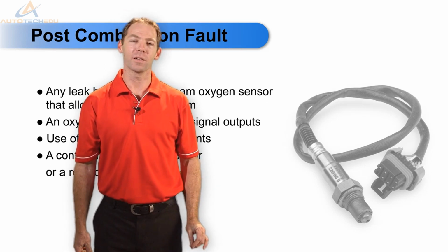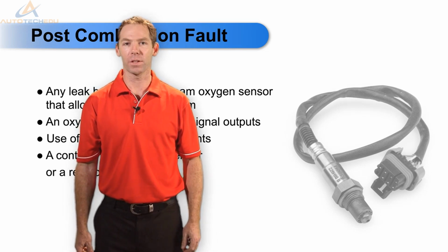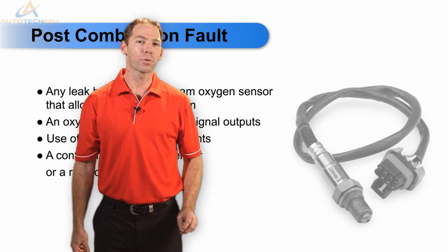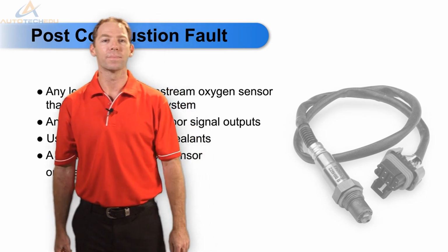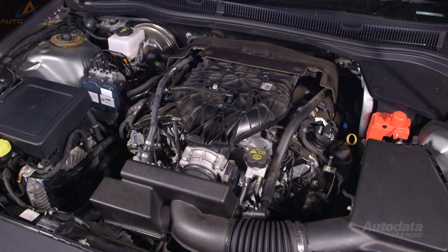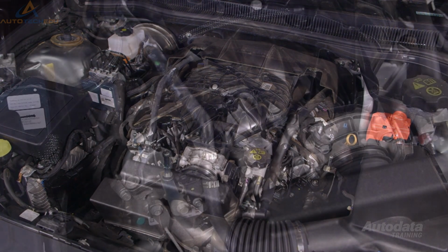Monitoring fuel trim data when looking for faults makes perfect sense. These parameters can be found in the OBD section of most scan tools. This makes diagnosing a misfire on a multi-cylinder engine relatively easy.